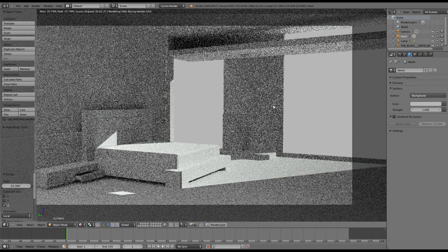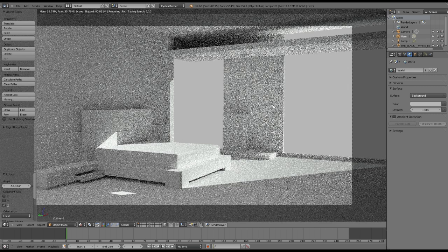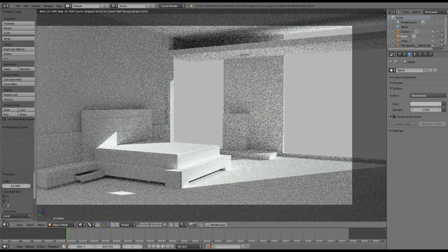But yeah, an extremely powerful thing to be able to rotate and move elements while inside the render engine. Right, so that pretty much clears that up. If we want to speed up our render, we've done pretty much everything. So you now know how to add materials, you know how to add a lighting hemisphere source, and you know how you can rotate that while you're rendering.